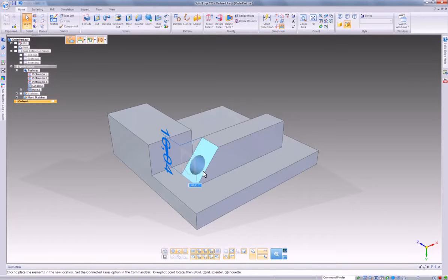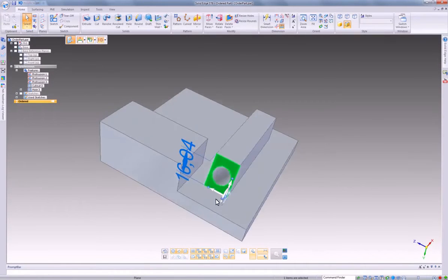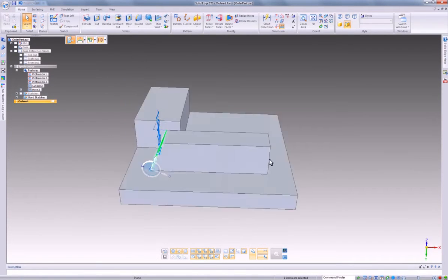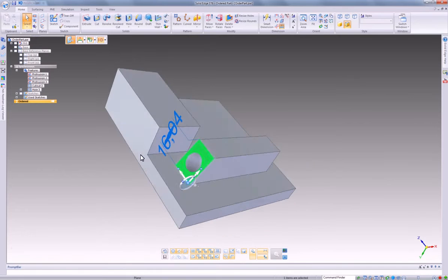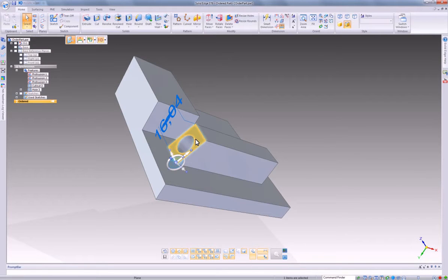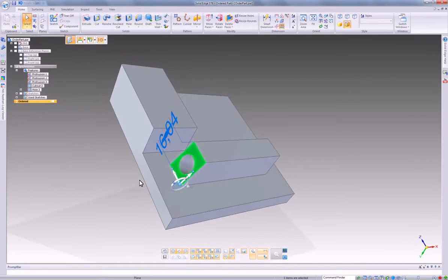And then we can rotate this face. But you'll notice that even though we're making this change, some of the default behaviors of synchronous don't give predictable results as well. Notice the hole is actually maintaining its relationship to that front face and moving it down to the part, instead of maintaining its extrusion all the way through this block where it initially started. So it's not really predictable from a user standpoint what the behavior change is of just that front face being angled or tapered in this condition. So this gives you a very simple example of some of the user's unpredictability of what will occur on these simple changes in ST6.